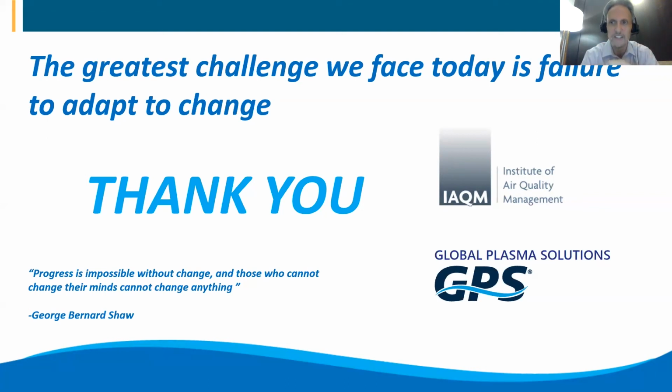So you can tell that the space is ionized more highly now than it was perhaps in the past when you turn the device on. As far as ion concentrations, what we typically recommend is that you try to create ion concentrations in the space that are anywhere from 2,000 to 5,000 ions per cubic centimeter higher than they were without the device on. If you walk into a traditional office environment, for example, and I've done this hundreds of times, I can almost guarantee you that you'll see ion concentrations somewhere in the area of 400 positive and 400 negative ions per cubic centimeter when you count them on the handheld particle counter.